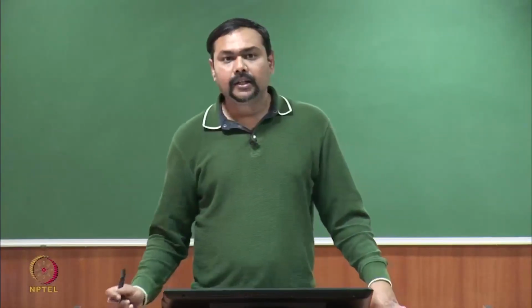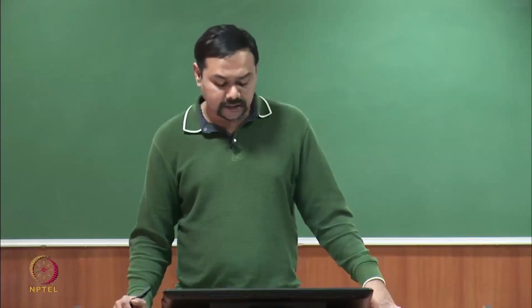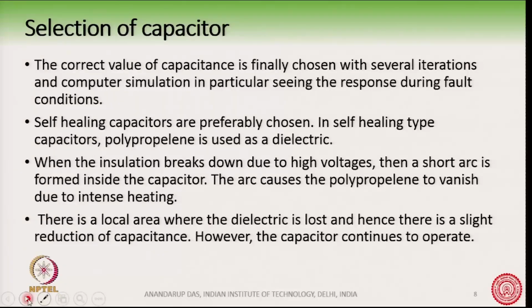The correct value of capacitance is chosen with several iterations, and in particular by seeing the response during fault condition, how the capacitors discharge their energy. Now, generally the self healing type of capacitors are chosen.